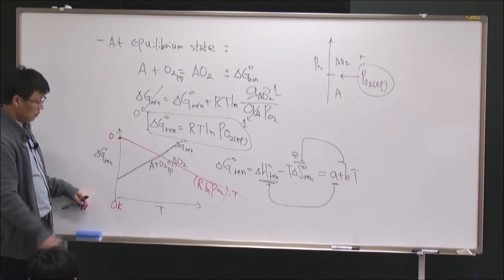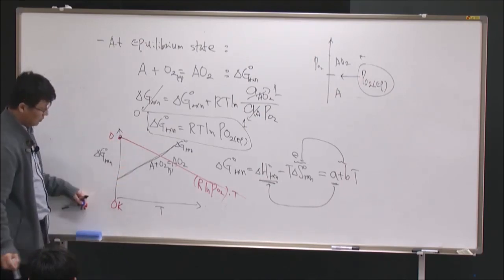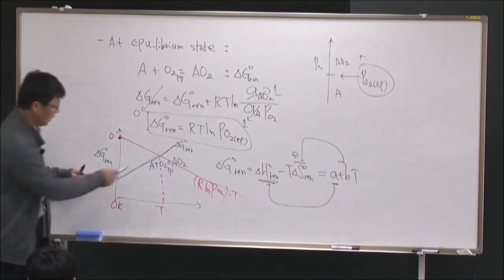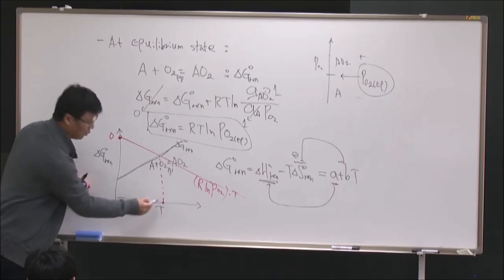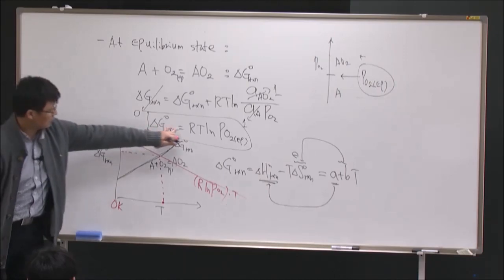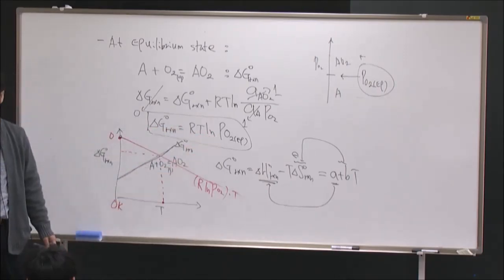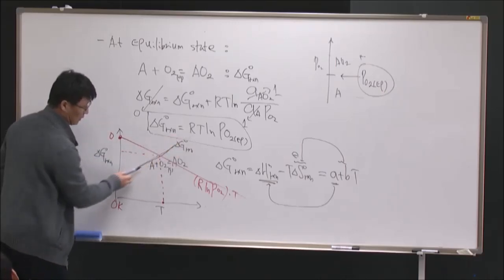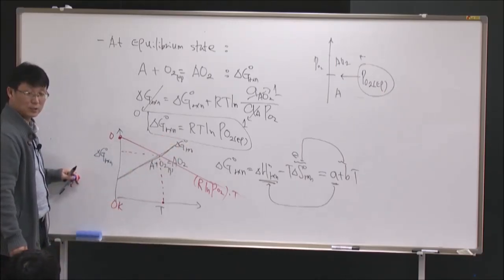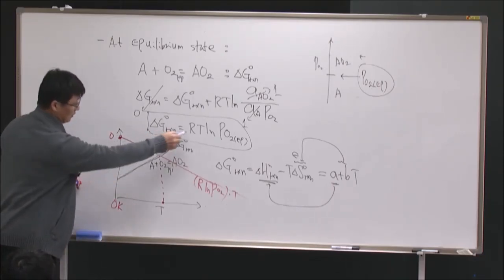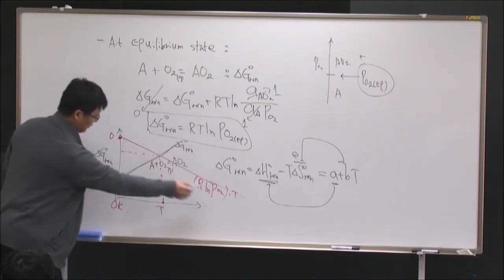So when I draw this kind of graph, I want to calculate... basically, this is the idea. Let's assume mathematically, if I want to calculate at this temperature T1, I know this delta G naught of reaction, so I can enter it here and calculate PO2. That's the mathematical way. Instead, the graphical way: if I have this graph of delta G of reaction here, I just plot it in this diagram. Then I plot the second line, delta G equal to RT ln partial pressure.